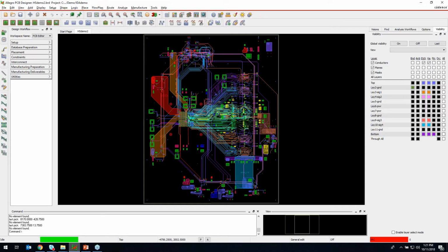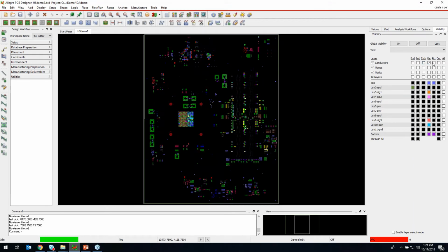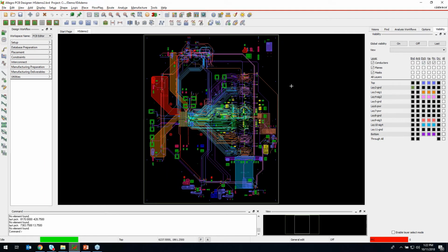So what I'm looking at here is I've opened up the Cadence toolset. I'm looking at a board that's a DDR4 design. If I turn off the etching, you can see with the pin layout that I've got a controller over here on the left side, and two DIMM sockets for my DDR memory devices. So I'm primarily going to be focused on looking at the signal analysis from the controller over to these memory devices. That's my test set, if you will.